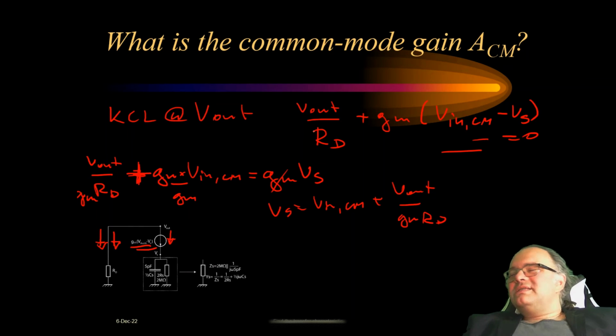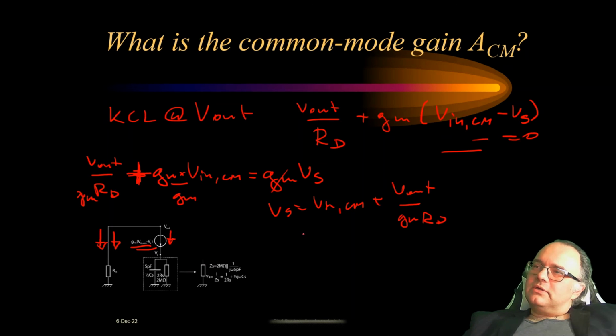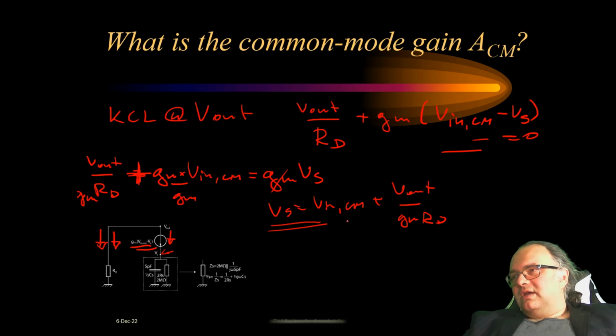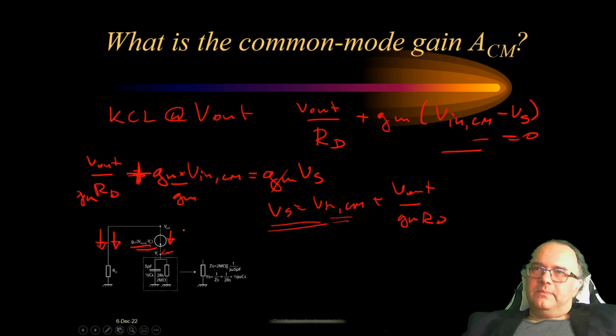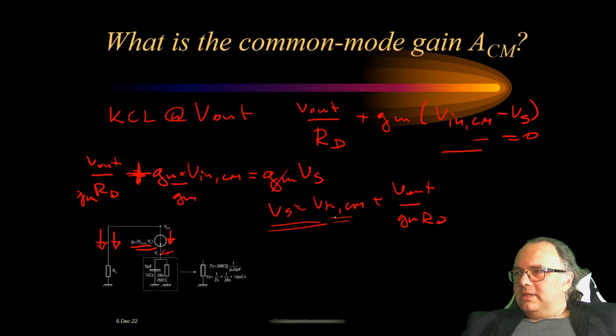Now at this point, if you want to take shortcuts, you can say that this is just a source follower. So the source voltage here is almost following the input voltage, and you can ignore this. If you want to be more accurate, you can keep it. So it's a question of accuracy of the analysis. If we want to eliminate Vs, we can consider the Kirchhoff current law at this node.